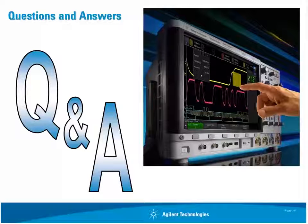So setting your time-based range is one thing. Also, most scopes, it depends on what you have turned on. Do you have complex measurements, FFT turned on? Those types of things will typically slow down a scope's update rate. Do you have serial decoding turned on? Do you have the MSO digital channels turned on? That will typically slow down a waveform update rate. Some scopes you can manually turn off sin x over x to improve.